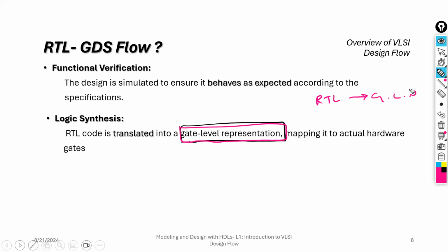Am I right? So that is the responsibility of logic synthesis, converting the RTL code into a gate level netlist, because of the gates or cells that are available in the standard cells. We'll talk about the term standard cells a little bit later, but this is simply a translation.